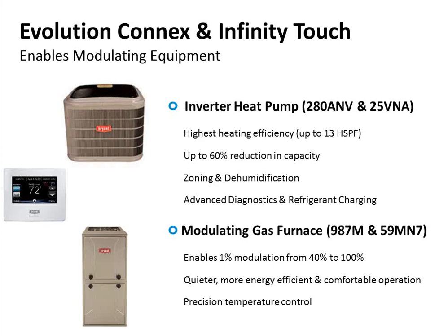The reason being is you got a modulating gas valve, you got a variable speed inducer, you got a variable speed blower, you got a modulating compressor, you got a modulating condenser fan, and then you got a 600-step expansion valve that's electronically controlled. You got 6 things that are basically modulating. So somebody's got to coordinate all that crap, and it ends up being the thermostat. So with that modulating equipment, you really have to use this thermostat.